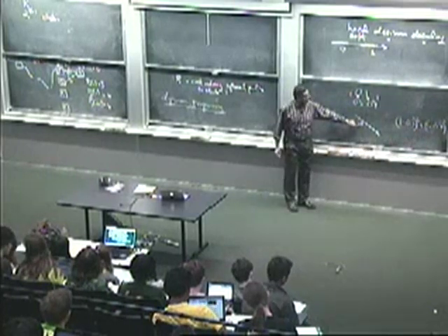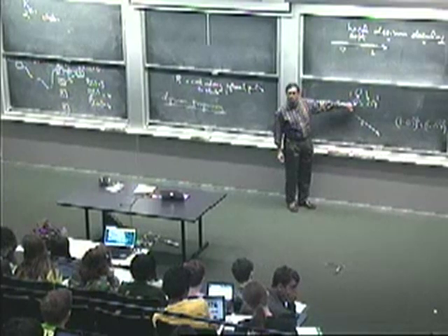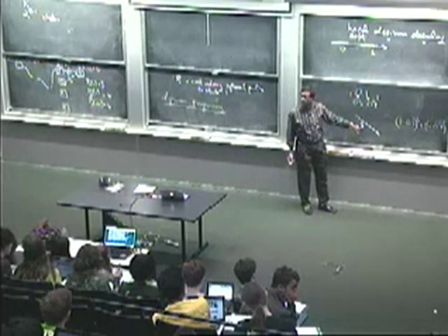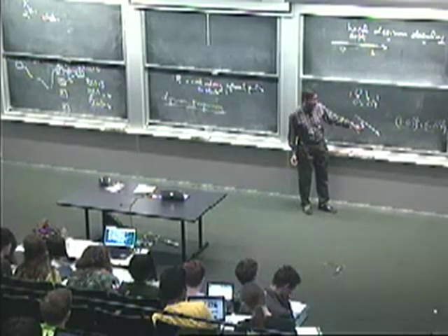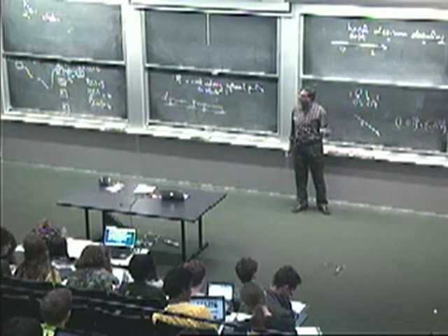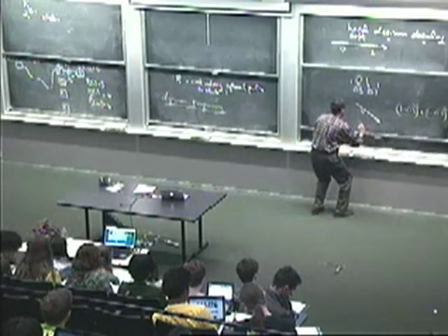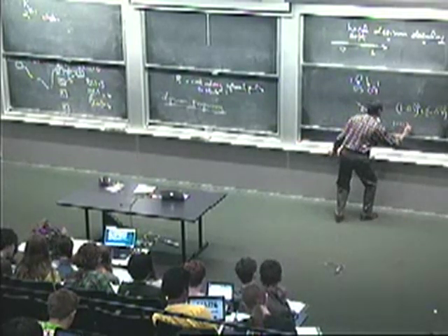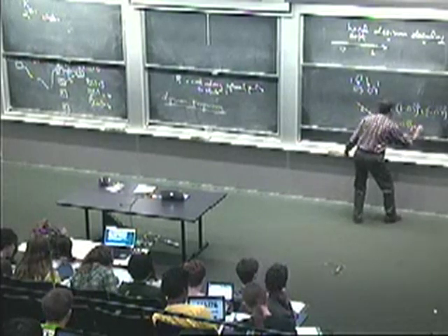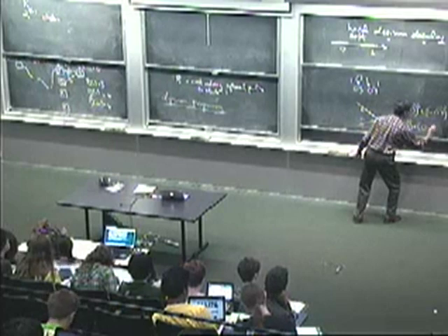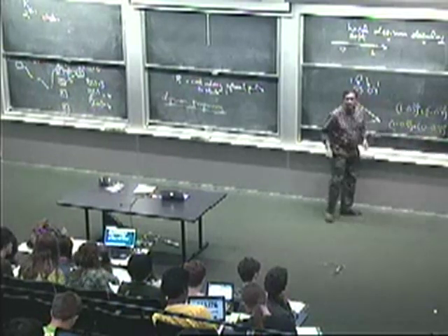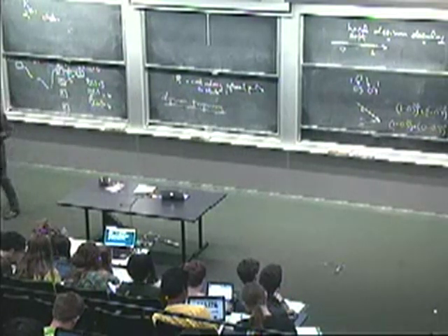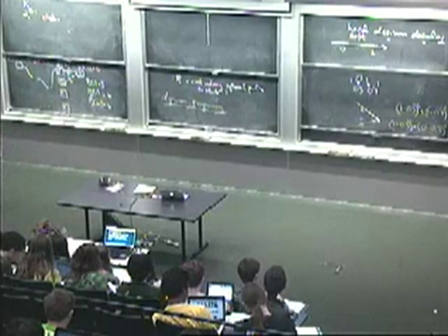Okay, so it would be the first bit that you emit on this arc minus the first sample that you got, squared error, plus the second bit that you would emit on this arc minus the second sample, whole thing squared. If there was another arc that was a 1 and 0 arc, then what you would compute is 1 minus 0.3 squared plus 0 minus 0.7 squared. Okay, so it's just a different way of coming up with the cost. The rest of the Viterbi algorithm is exactly the same. The navigating through the trellis is exactly the same.